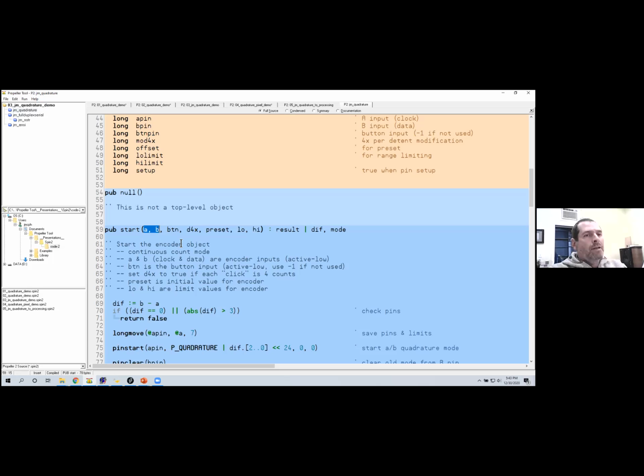For example, could I have one of my quadrature pins on pin 31 and the other on pin 32? I haven't tested. I should. No, I don't think it matters. No, you can cross those boundaries for smart pins by using the plus or minus 3. Yes, it's plus or minus 3. You can cross those boundaries, and it even wraps around at the end, and it wraps under at the beginning. I think that Clouseau used that feature in what he was doing with his video thing.